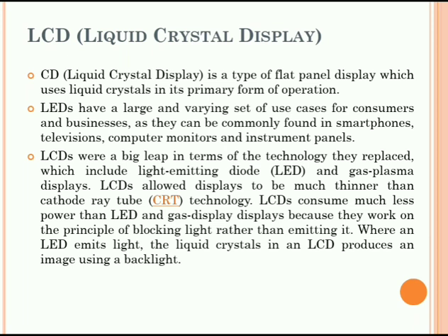A polarizer is applied to the front and an analyzer with reflector is applied to the back of the cell. When randomly polarized light passes through the front polarizer, it becomes linearly polarized. It then passes through the front glass and is rotated by the liquid crystal molecules and passes through the rear glass. If the analyzer is rotated 90 degrees to the polarizer, the light will pass through the analyzer and be reflected back through the cell. The observer will see the background of the display, which in this case is the silver gray of the reflector.